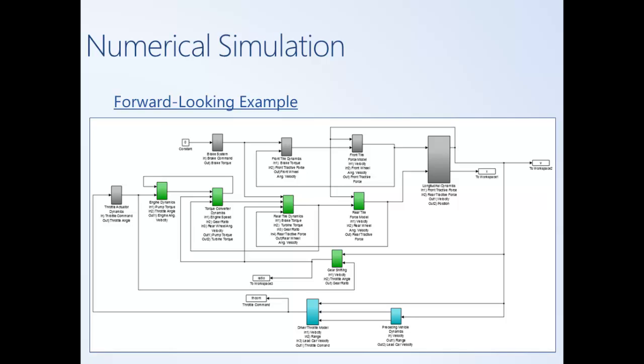But what we're doing is modeling the driver, and the driver is taking these desired velocities as inputs. It's also taking the distance of the current vehicle to the vehicle preceding it on the highway. And based on those inputs, it's generating commands. So in this case, a throttle command where we're presuming that the brake command is 0. So this is just basically only modeling an acceleration.